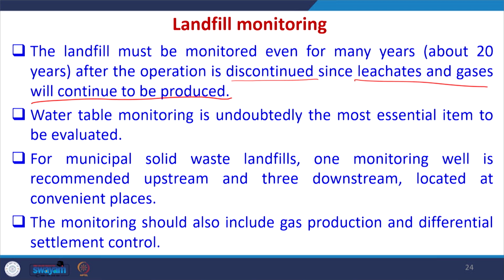For a municipal solid waste landfill, 1 monitoring well is recommended upstream and 3 downstream, located at convenient places. So, we can have 4 monitoring wells, 1 upstream and 3 downstream. The monitoring should also include gas production and differential settlement control, because the movement of the landfill may also happen sometimes.